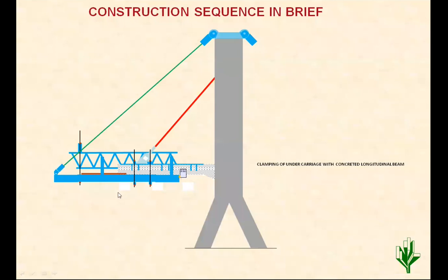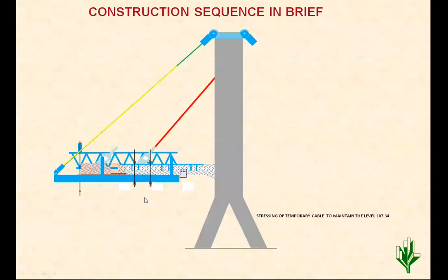Now this is ready for the concreting of this 6.3 meter. Now again for the next segment the anchorage is placed, reinforcements are tied, and conventionally concreting is done for that segment. Once the concreting is done, the stress in the cable goes on increasing and this point also goes on down. So now again the same procedure will be repeated till the end of the bridge, and this is symmetrical, for the presentation purpose, though it is shown on one side. This has been done symmetrically.